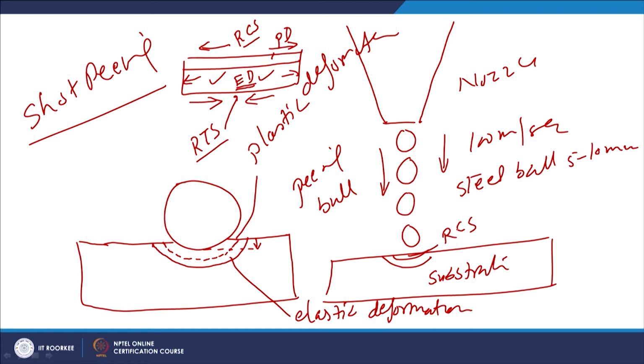Since these kinds of stresses are developed due to plastic deformation of the near surface layers, whatever layers are being deformed plastically will be strain hardened or work hardened. So, this kind of work hardening will lead to an increase in hardness due to the strain hardening effect.